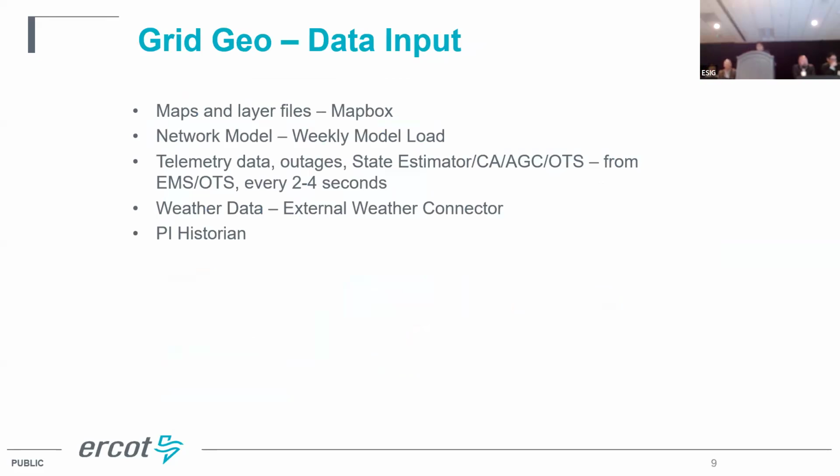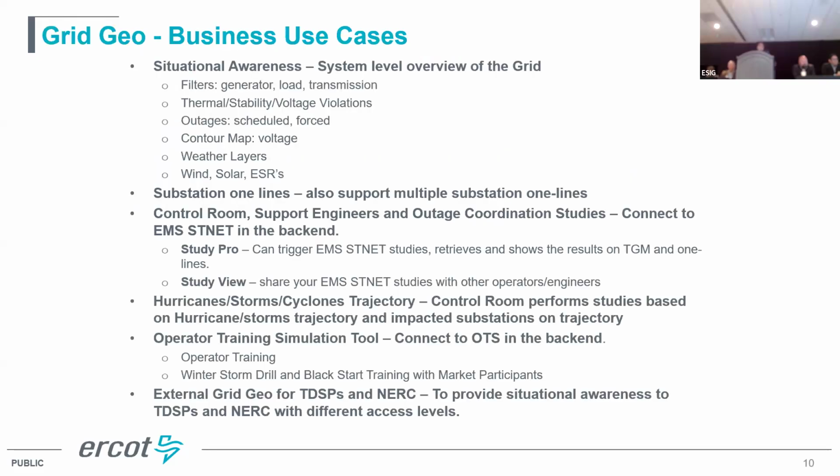And the energy management system data sets are the real-time data sets that I'm referring to. We have 2 to 4 second data sets, 10 second data sets that keep this information very, very real-time, so decisions can be made based on data that's available on the screen.